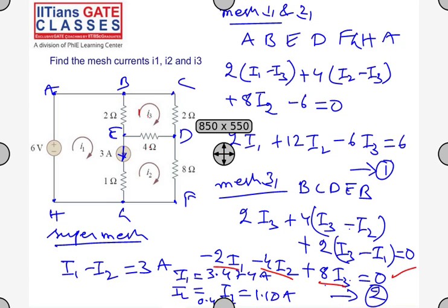If you observe this, the 1 ohm resistance is not used anywhere. The value of this resistance is irrelevant, because whatever the current from this source, 3 amps will flow through this resistance, and you don't need to find the current through it separately. This current source forces 3 amps through this resistance. Only when you consider the power consumption will you consider this resistance. Otherwise, you don't have to consider it for finding the currents and voltages across any element. Any doubts? Am I clear?